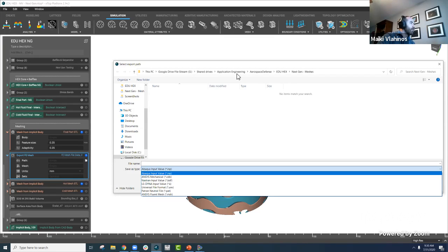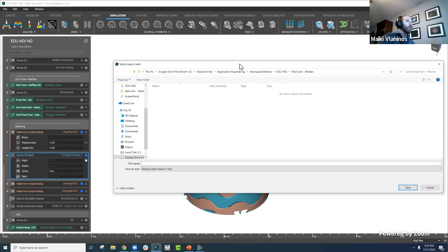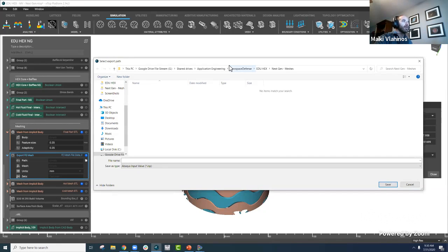What mesh format do I recommend for Ansys? It depends on what your overall goal is and where you're at in the design process. If you're early in the design phase, I definitely recommend just using an STL and going straight to Discovery Live if you have that capability.